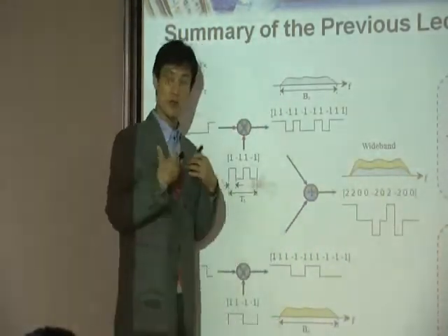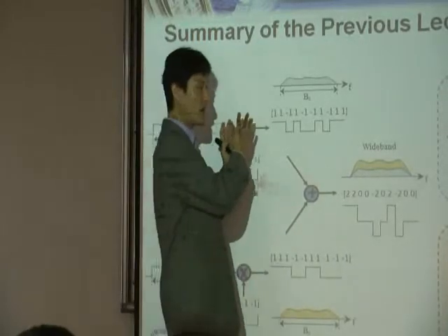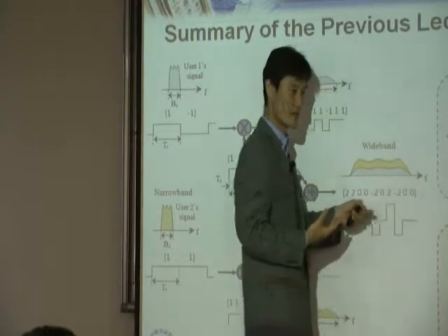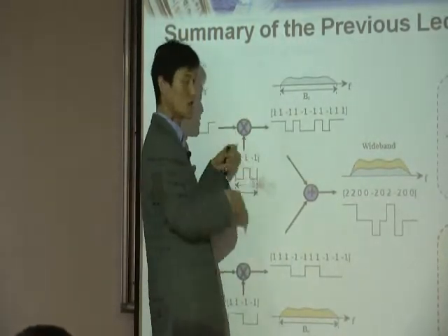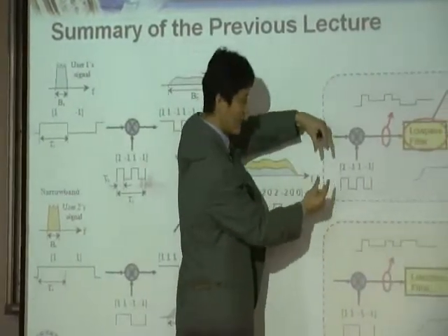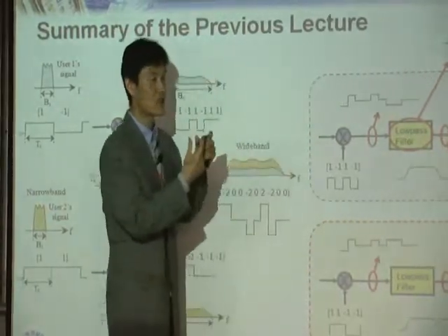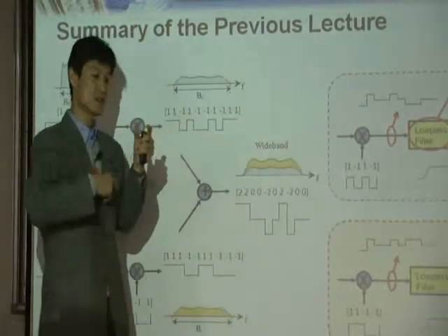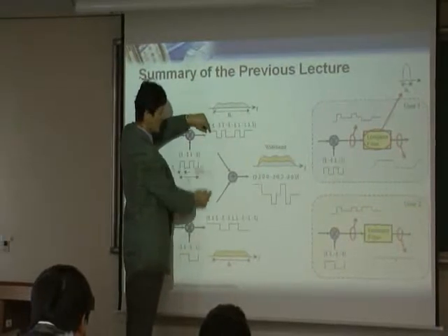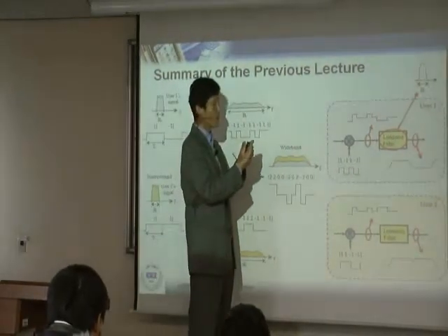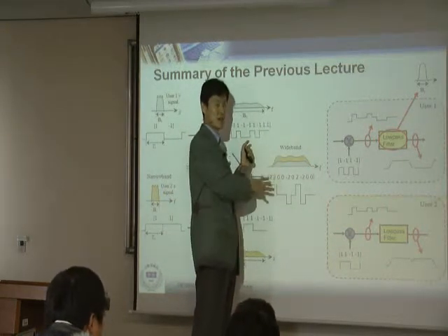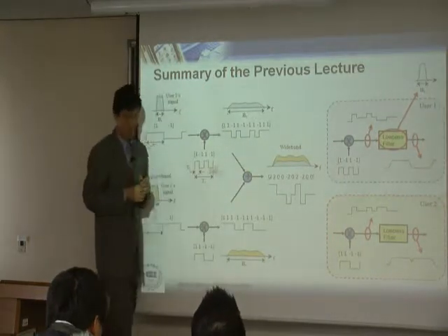What we are trying to do for each user is that when I transmit a packet, that packet has to be received at the exact base station's time. That's what we are trying to do, right? That way we are talking about synchronization. So that's why they have to do synchronization when they wake up. Each one wakes up and each one does a synchronization. So ideally speaking, when each guy transmits, these packets should be received in an exactly synchronized fashion. So certain synchronization is already there by the process. Since we are doing such synchronization, it is very unlikely that you are way off, because your chip is already synchronized by the process. However, small offsets can happen because of the fading, because of the delay multipath. That's what I'm saying.